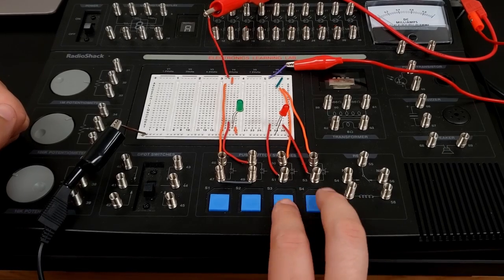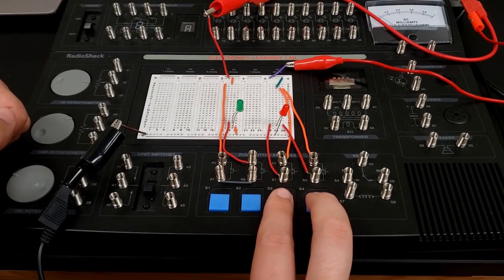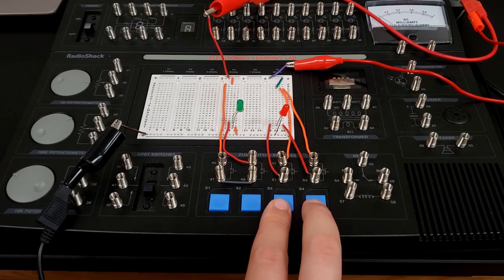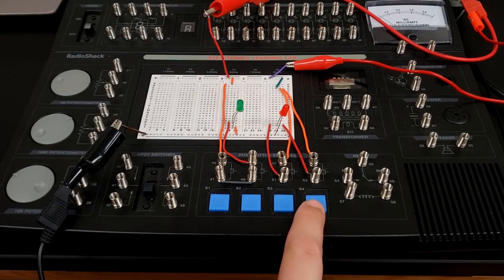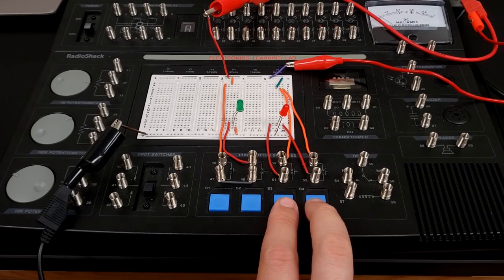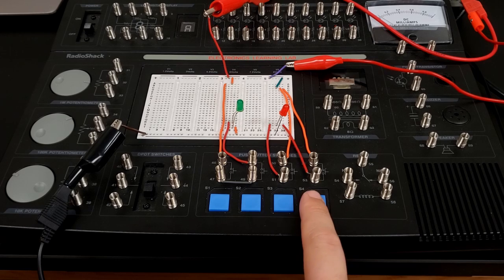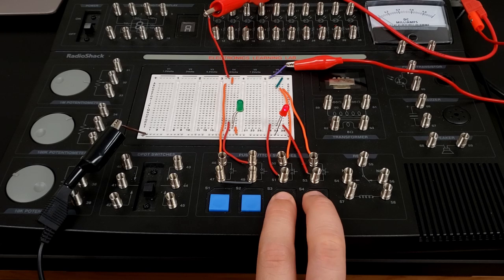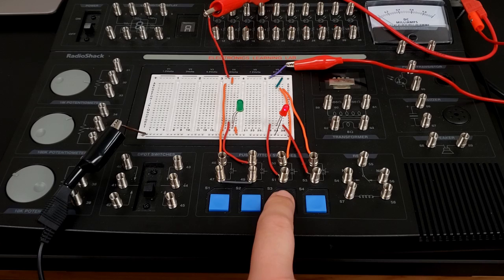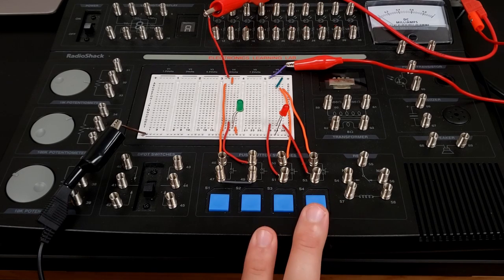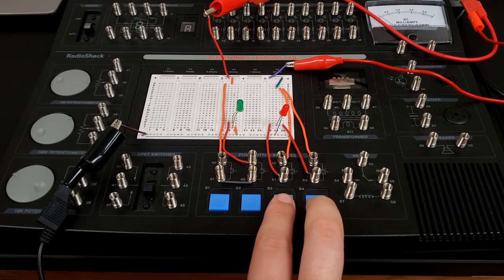Now, for the parallel circuit, we have it hooked up to S3 and S4. Here are our 2 switches in parallel, and this is going to be our OR gate. Right now we have neither one of them pressed, and you can see that we have no output, which is consistent with our OR gate. If I press just one, S3, you can see that red LED lights up, so 1, 0 in this case has a 1 output. Now if I do 0, 1, so I press this second switch, you can see that also has an output. And if I press both at the same time, we again have an output. So our truth table for this one would be 0, 1, 1, and then 1 for the output, which is consistent with what we talked about for an OR gate.